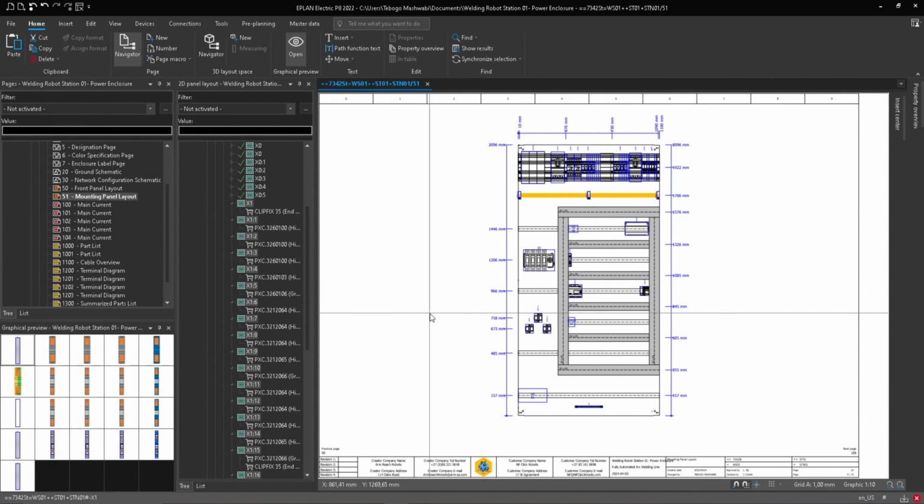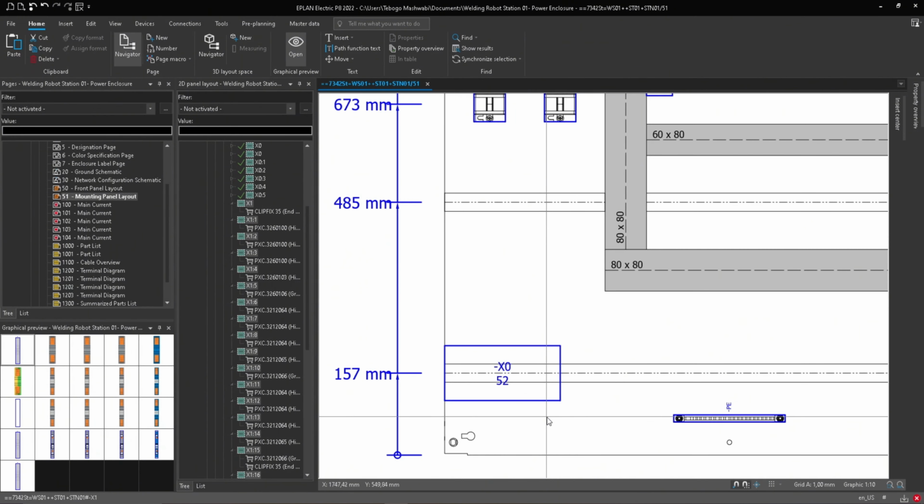So moving right along, another question raised by one of the students was with regards to placing components onto the mounting panel. The question was mostly related to placing components such as terminals. I showed them how to place terminals as a complete terminal strip. You can see this X1 doesn't show terminal number 1, terminal number 2, terminal number 3, terminal number 4, and so forth.